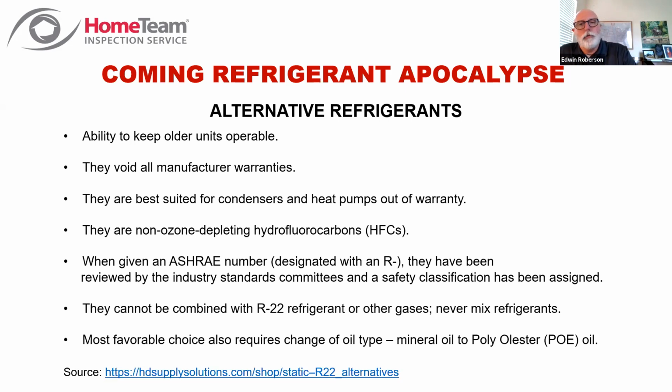They've been reviewed by those industry committees and safety classifications have been assigned. They can't be combined with R22 or any other refrigerant. The most favorable choice, the one that performs most like R22, also requires a complete oil change of the system.